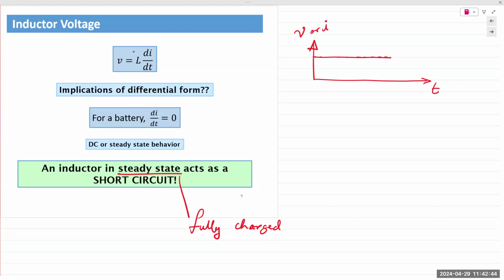It's not a direct opposition. It does not oppose the current itself, but it opposes any change in the value of that current. Meaning if you initially applied 5 amps and now it changes value to 4 amps, it is going to oppose that change. It will still go to 4 amps, but will oppose that change while it's still transitioning.